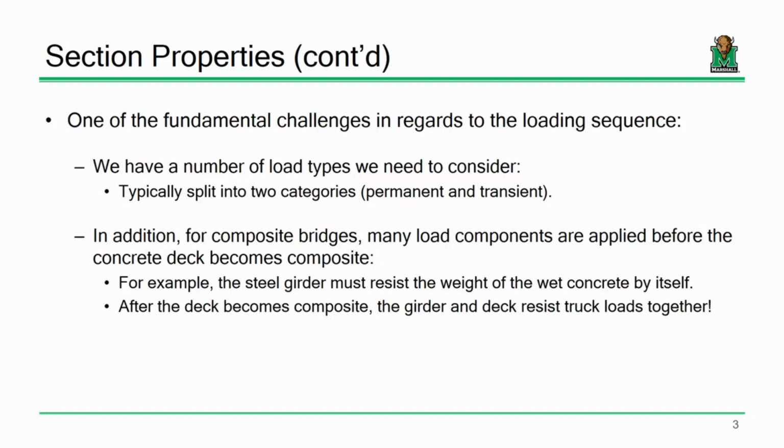So what happens? First thing I do is I take the beams, I set them down, right? Okay, so what loads are the beams subjected to right then? What loads are they subjected to? What's that? They have to support their own self-weight, right? Obviously, all beams have to support their own self-weight. Well, what is resisting that load is the steel beam by itself, just the steel beam, okay?